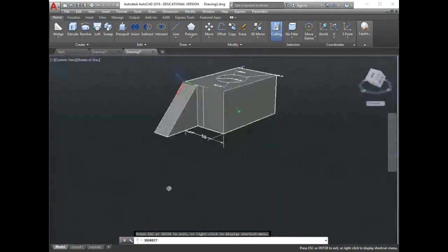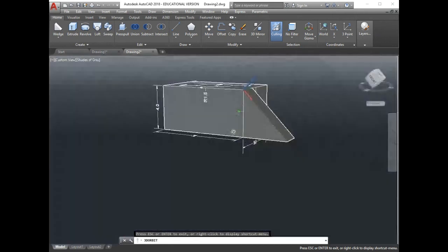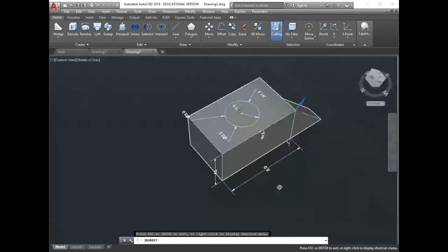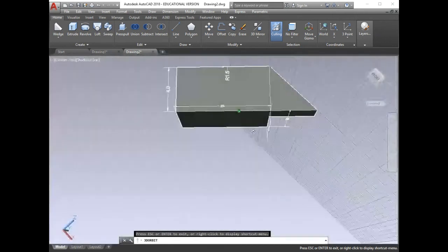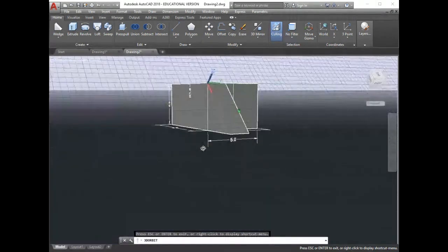You have to do this step, guys, before you proceed, because sometimes you pick the wrong point, so the two lines look like they coincide, the two planes, but actually they are not, they are intersecting. So be sure before you proceed and put your dimension to make that orbit view, and be sure that they are both parallel, not intersecting.